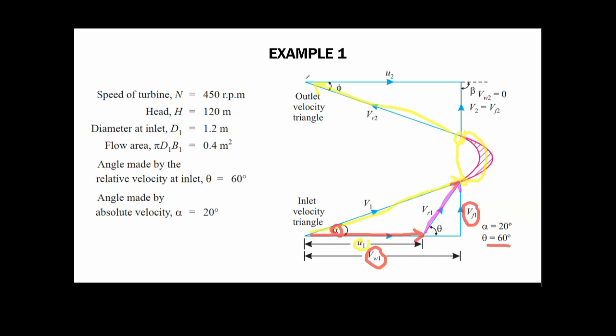Okay, and now U2, the velocity of the vane, is given by this arrow, and you can see clearly here that U2 is larger than U1 because the vane got energy from the jet, okay, from the water, which transfers into kinetic energy that moves the vane faster than before.